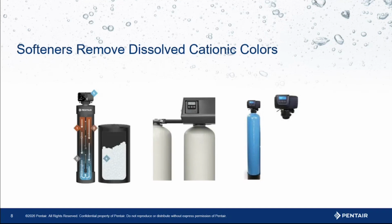Another caveat to this is short-term rental properties with water softeners. The longer you leave soft water unflushed out of a copper pipe, it's going to dissolve some of that copper. Water softening systems in copper plumbing are designed to be used, not static. So understand that if there's long durations between occupancy, as short as a couple weeks, a month or so, you may see color come off the first purge of that system. And that's more of a flushing than a treatment circumstance.